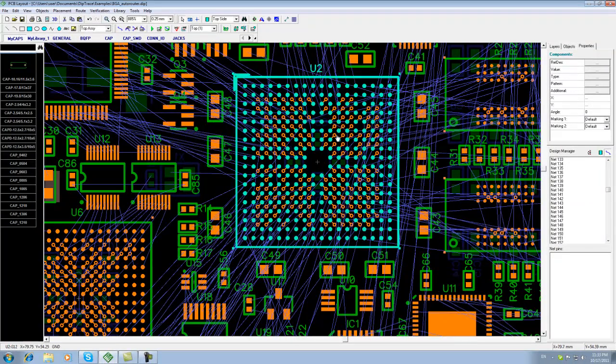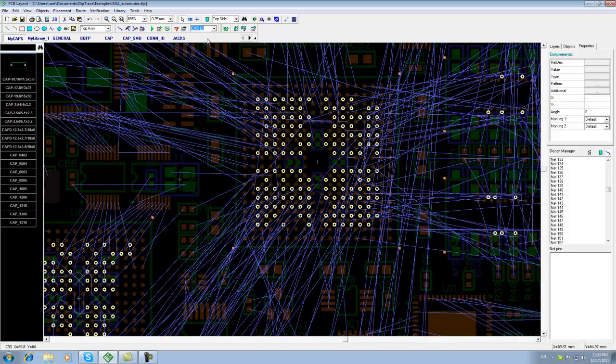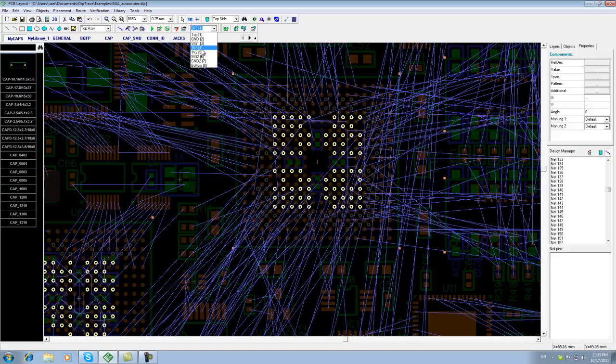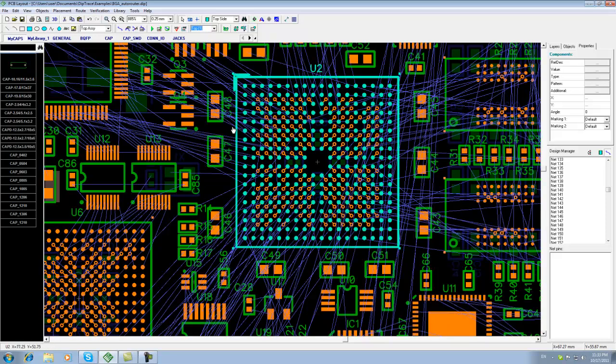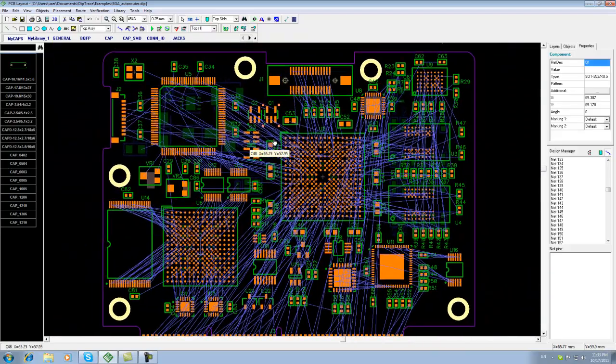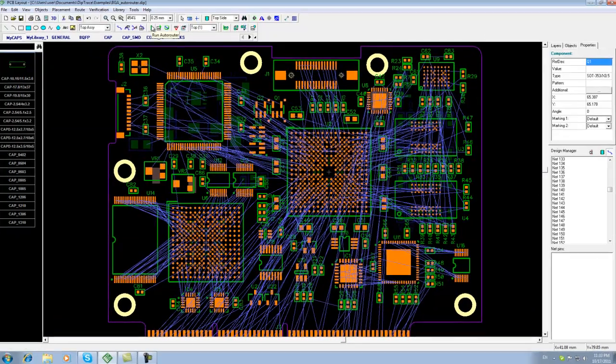You can see. Also, we have used vias for connected pins only in it. Okay, you can also check how it is done in all layers. Signal 2, ground. Okay, the next step will be auto routing. Press run auto router.